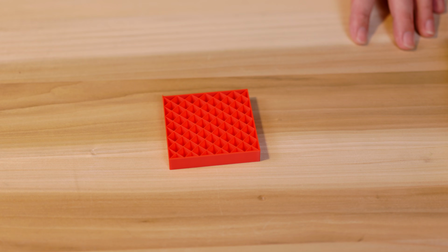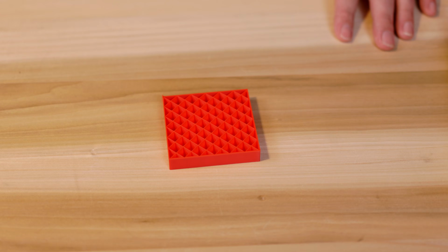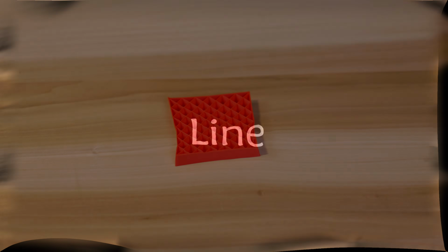A printing tip for this is adjust the distance for optimal strength and material usage. The time that it took for the cube to print was 1 hour and 2 minutes, and the material it used was 68.91 grams. So you will see a little bit faster than rectilinear and a little bit less material used for this particular cube here.